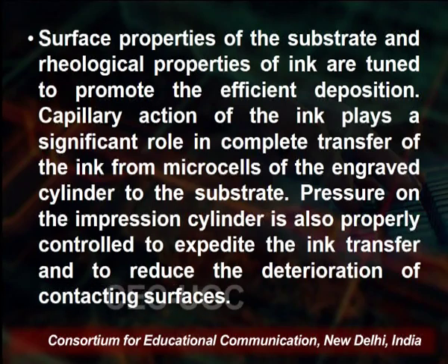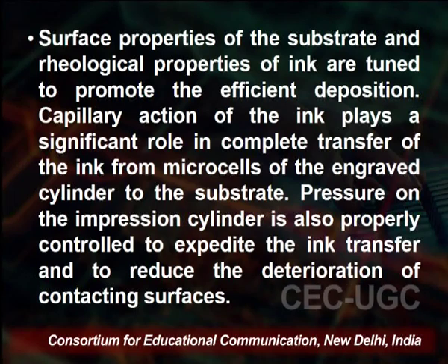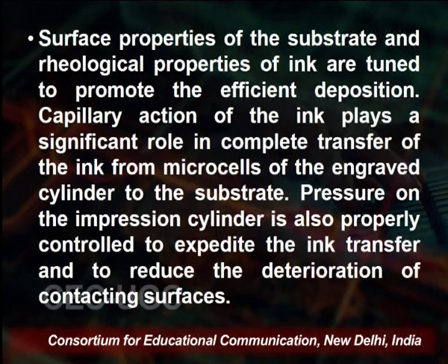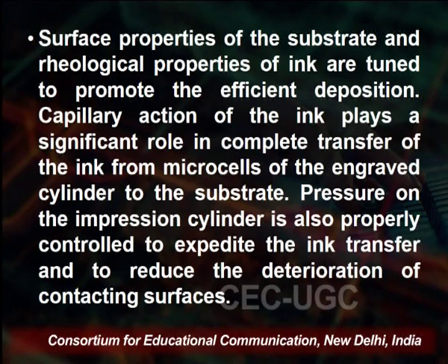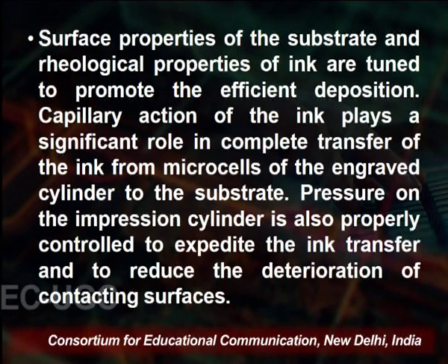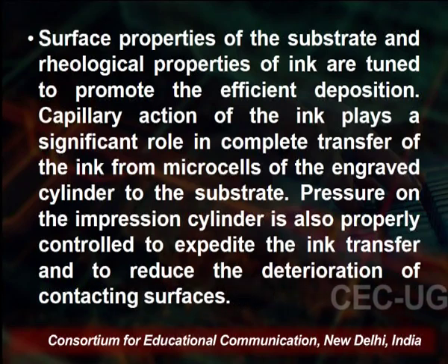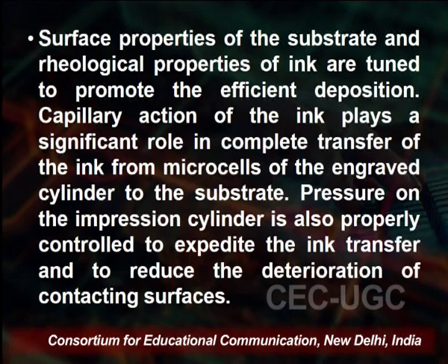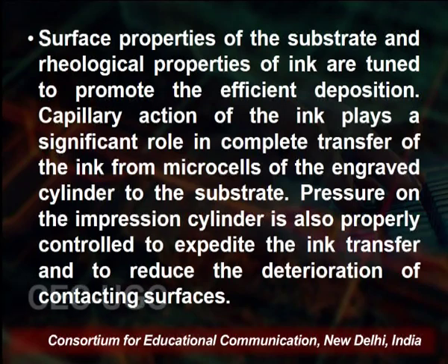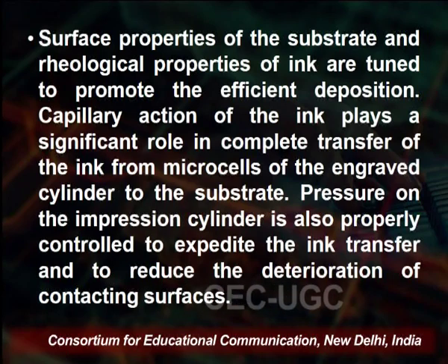Capillary action of the ink plays a significant role in the complete transfer of the ink from the microcell of the engraved cylinder to the substrate, and the engraved system will roll on the substrate and the pattern will be created on that substrate. The pressure on the impression cylinder is also properly controlled to expedite the ink transfer